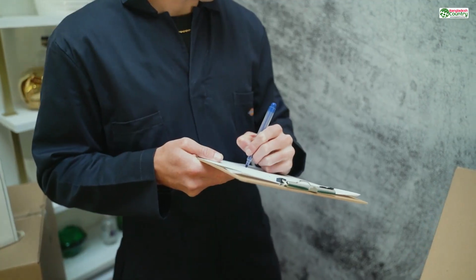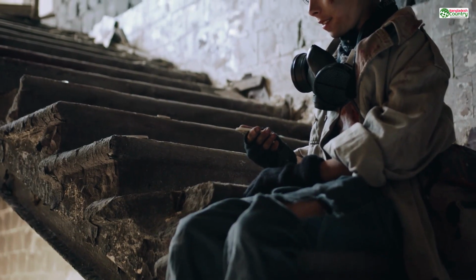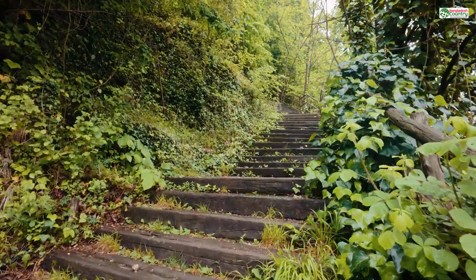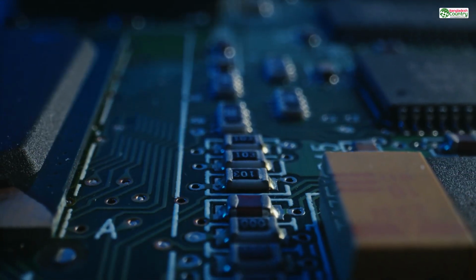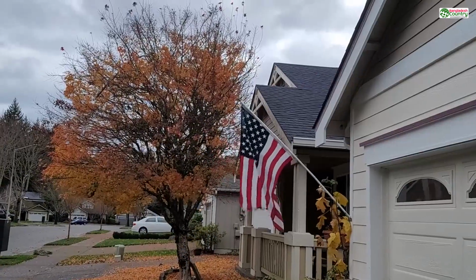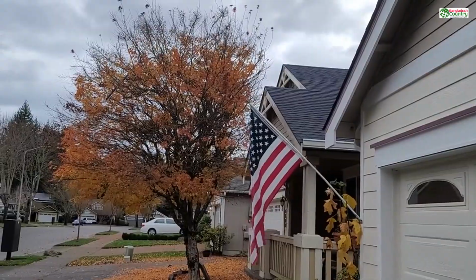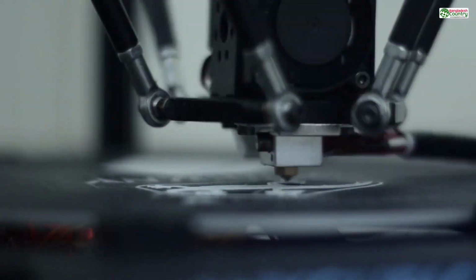When you step up to standard functional parts, things like brackets, enclosures for electronics, or simple tools, you'll typically want to be in the 20 to 50% range. This is the workhorse range. It provides a great balance of strength, print time, and cost. A part with 40% infill can be surprisingly tough and handle a good amount of day-to-day stress.